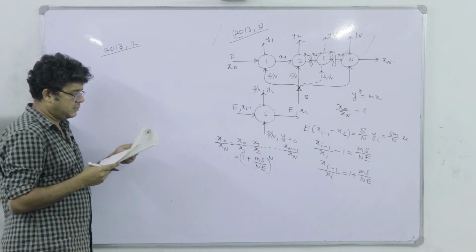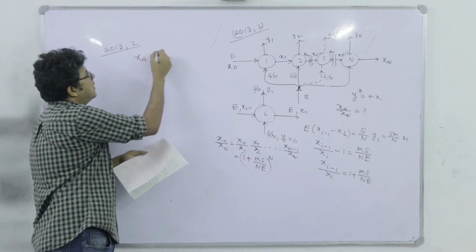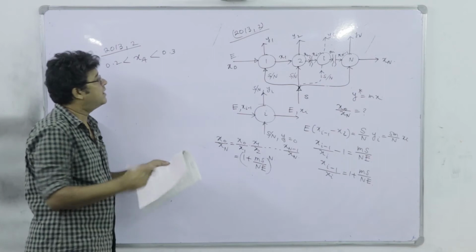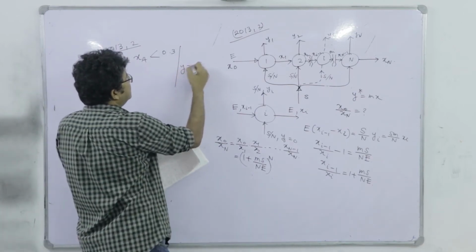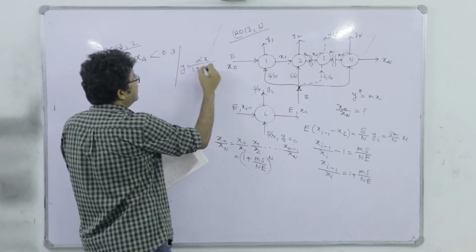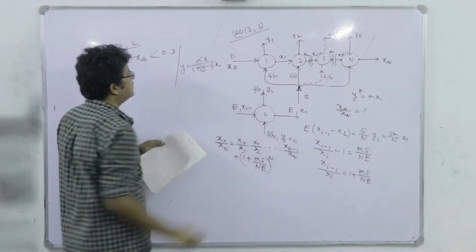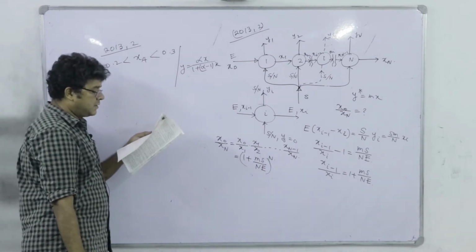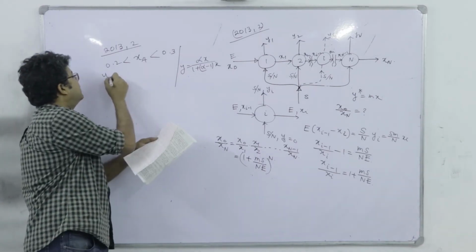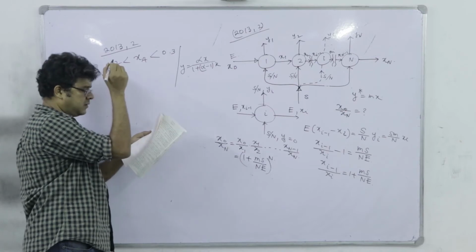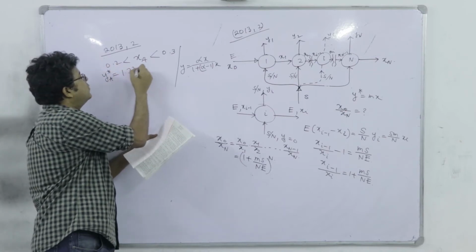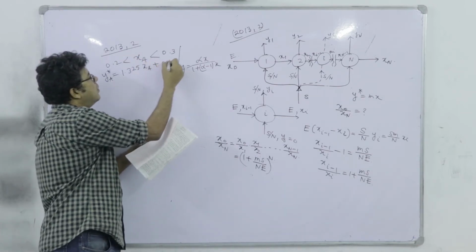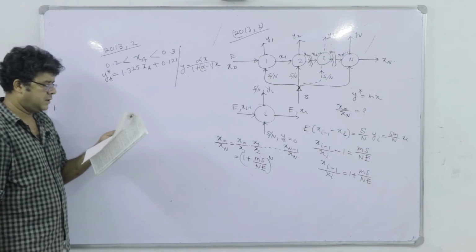range of liquid mole fraction, XA between 0.2 and 0.3. Generally the relation you know is y equals alpha x divided by 1 plus (alpha minus 1) x. But over this narrow range of 0.2 to 0.3, it can be safely approximated by a linear relation which gives ys star is equal to 1.325 xa plus 0.121. Right?